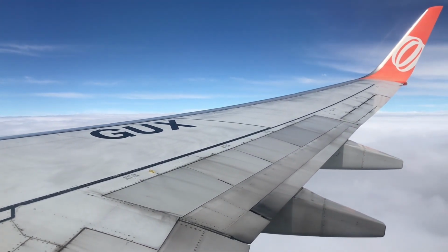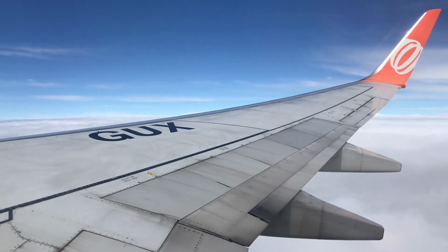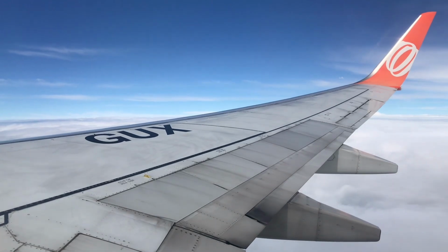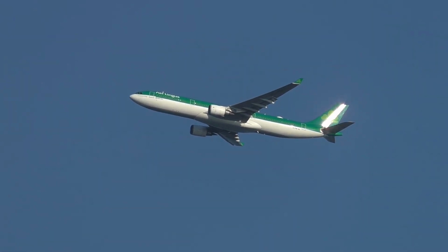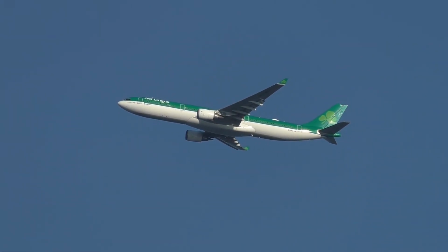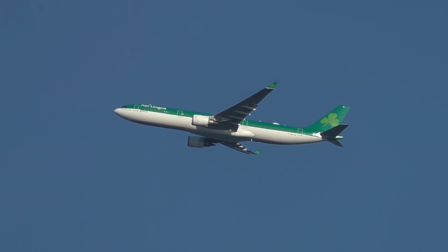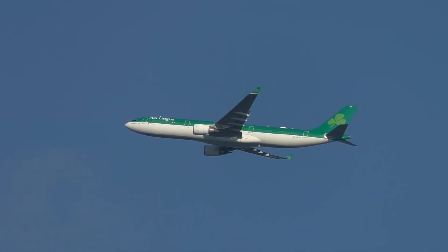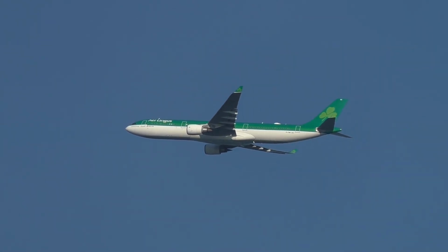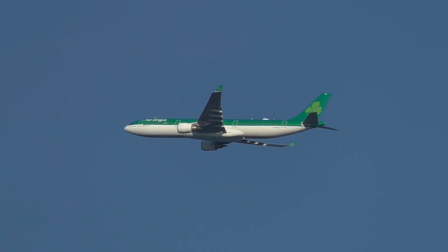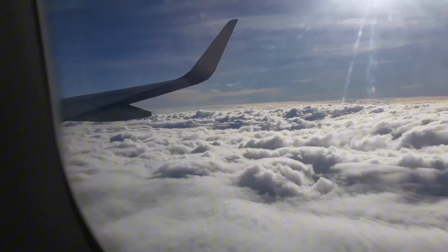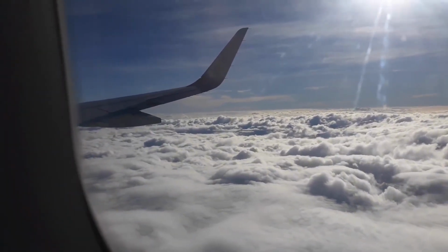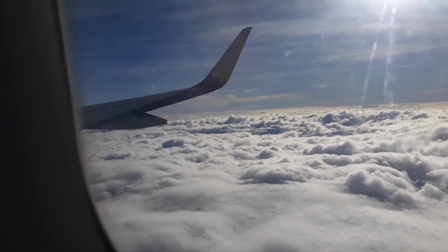One of the most important concepts in winglet design is something called effective wingspan. Even though the physical wing hasn't changed, aerodynamically, it behaves like a longer wing. And as we discussed earlier, longer wings mean less induced drag and better efficiency. Winglets allow aircraft to gain these benefits without increasing actual wingspan, adding excessive structural weight, or compromising airport compatibility. It's an elegant workaround, a small addition with a massive impact.